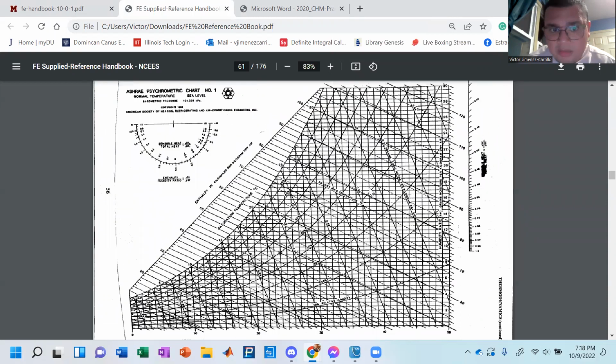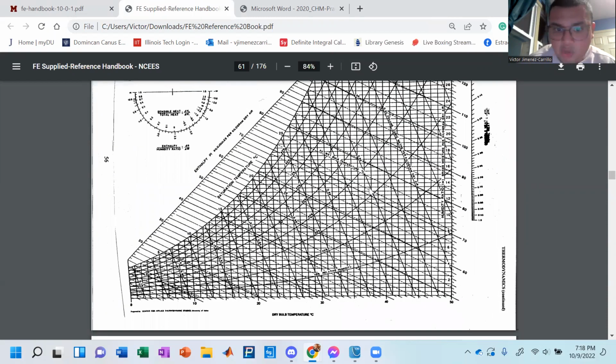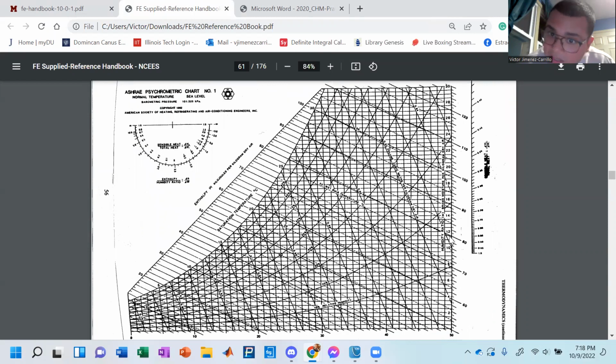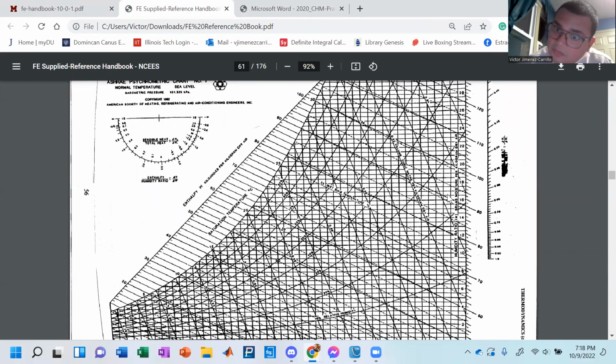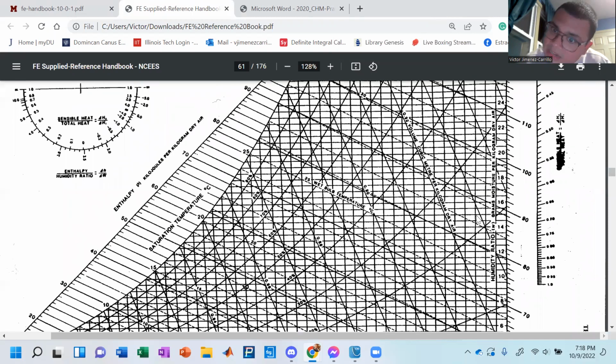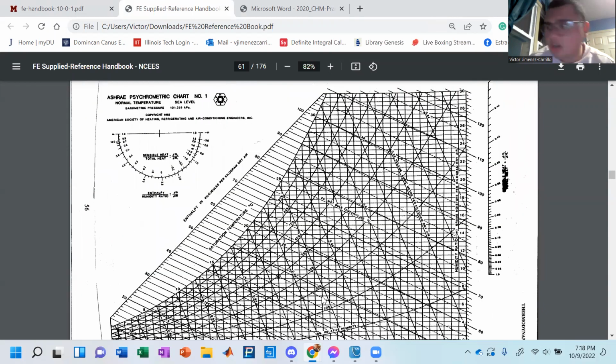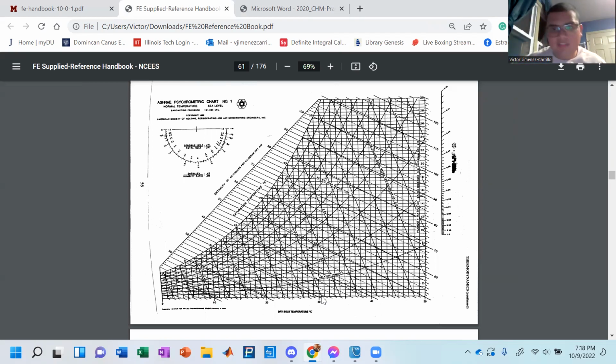This is going to describe your saturation temperature, your dry bulb temperature, and the humidity ratio, which is very important to see. That is grams of moisture per kilogram of dry air. Well, in our case, the question says we have this mixture of dry to wet air. The humidity ratio, HR, is equal to the grams of moisture divided by the kilos of air.